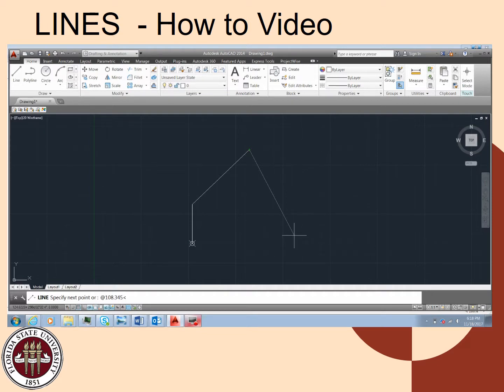Angle, now we'll give it degrees, minutes, and seconds. Now for the degree, the symbol is D. So in this case, it's 176 degrees, 123 minutes. And I'll need to give it the seconds, 34.45 seconds. And I'm just making this stuff up. So now it has installed the next length at the correct azimuth with the correct length.